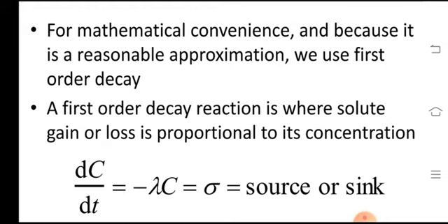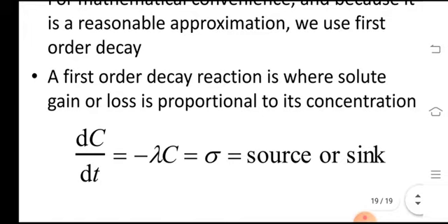And if our waters and monitoring wells show hexavalent chromium in excess, it indicates fresh intrusion of contamination from some source like wastewater coming from tanneries, which is very recently introduced into the medium, so it exists as hexavalent chromium.